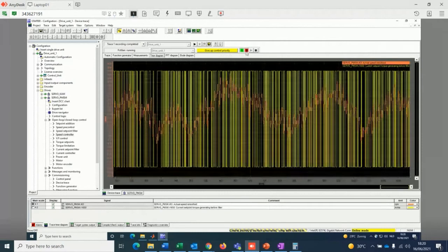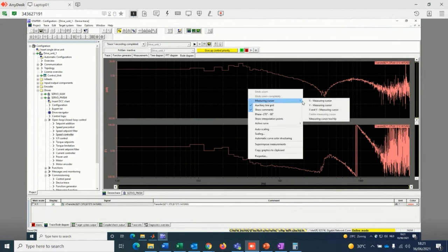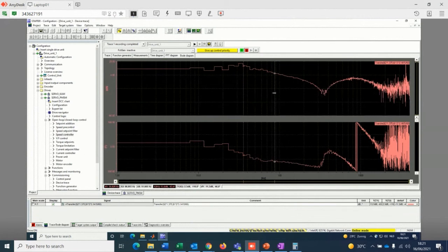So we can see that it sent us to the time diagram, but we need the bode diagram. So we will go to the bode diagram tab, and we can see how the filter suppresses the resonance peak. Now we will use this to design our system. So we will again use the cursor. So we go here, we tick the cursor.